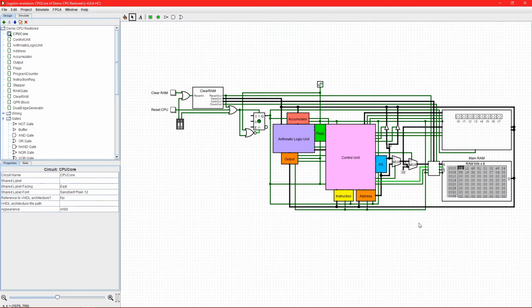So the first instruction loads 18 into register 0, and since all the displays here are in hexadecimal, it looks like it's 12. The next instruction pushes that 12 onto the top of the stack. So now the stack pointer has been reduced. It basically just wrapped around. There's no overflow protection on this stack, so if it overflows, it's just going to continue operating, but it might malfunction eventually, and you'll have an interesting time trying to debug it.